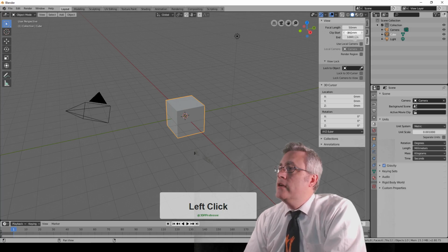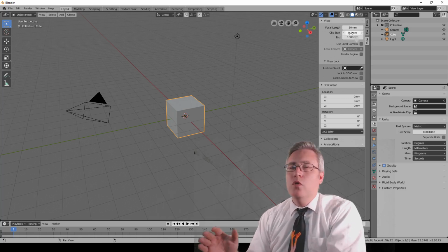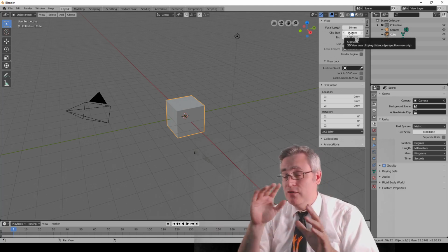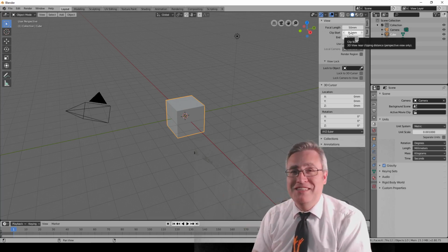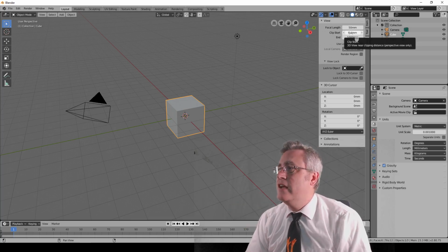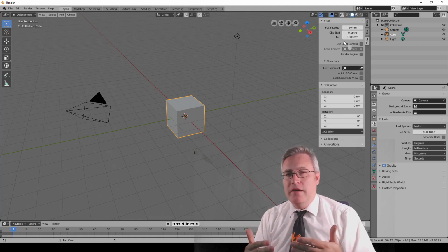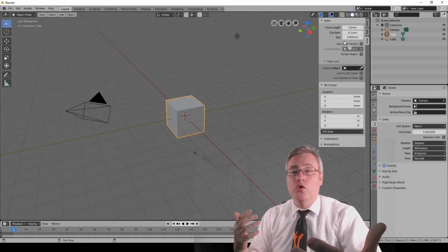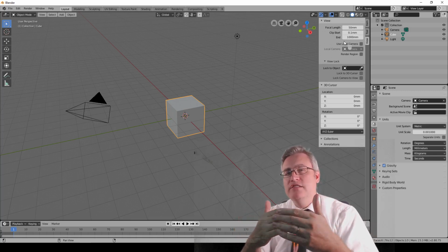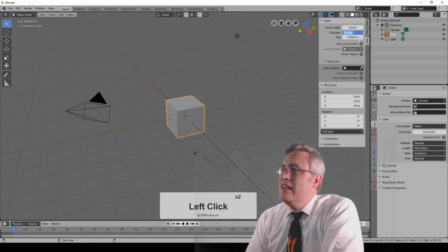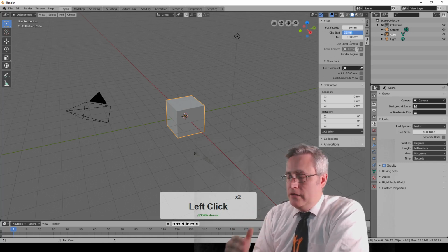right here, these first couple ones, focal length defines how the virtual lens of the virtual camera that we are looking through into the space is set. That's fine. But the clipping, to save Blender from having to render the entire world, it will cut things off after a certain distance. Now, I like my clipping to start a little bit closer, so I like to